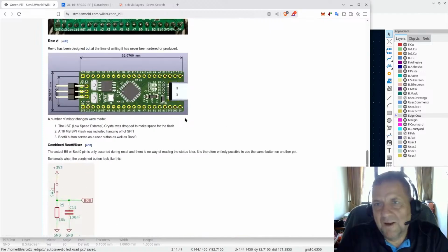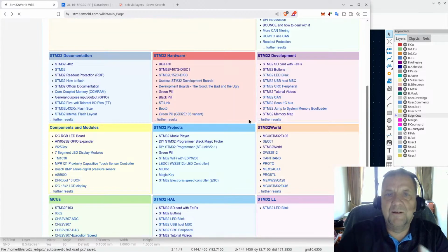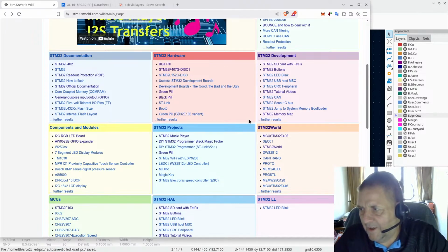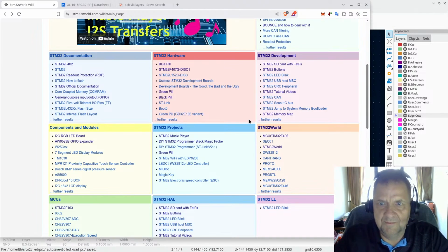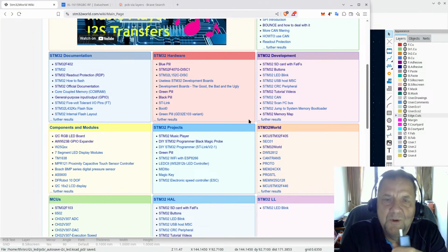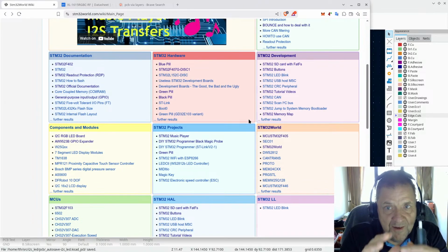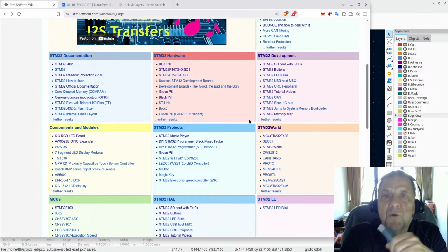So, I mean, it goes through revisions because typically, when you get the first version of a PCB, I would generally say if it can be brought to work, it's a success. By brought to work, meaning you might need to cut a trace, you might need to run a jumper wire or something like that. But at least if you do that and you can make it work, then you know what the problem was and you can easily fix that in revision B.